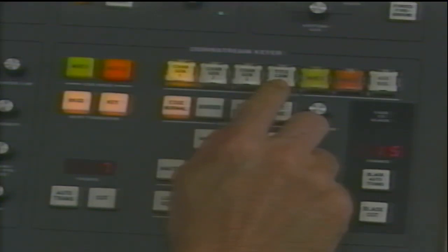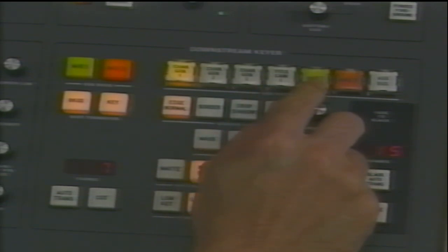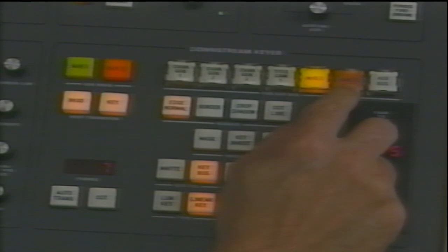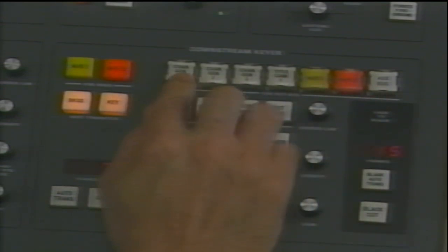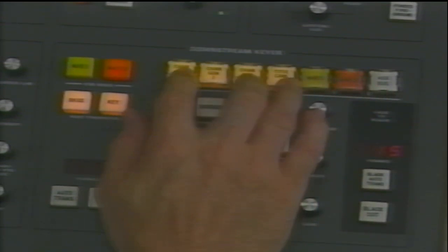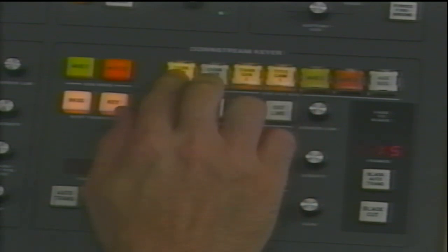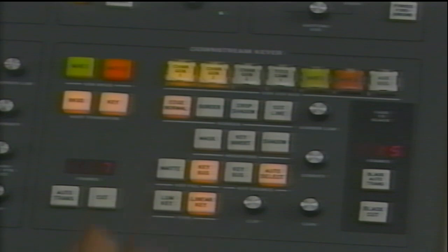The DSK key bus allows us to select 4 external fills: Mix Effects 1, Mix Effects 2, and Auxiliary Bus 1 as key fill sources. These sources can be accumulatively latched in any combination. The key sources can be external or self-keys as determined by personality programming. There are 4 external key sources in the DSK.